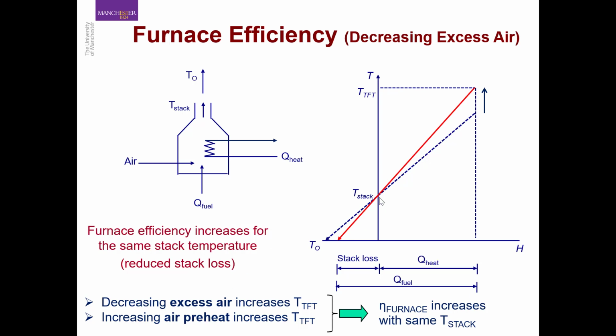But in case your stack temperature is very close to your dew point, then obviously you do not have enough temperature driving force available to preheat your air, and then you have to either decide not to preheat your air, or you have to use an external source to preheat the air to maintain a certain efficiency of your furnace.